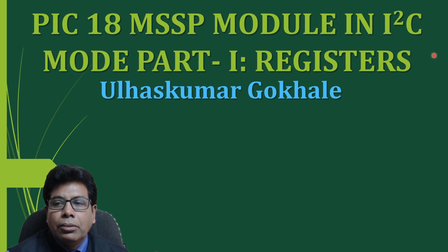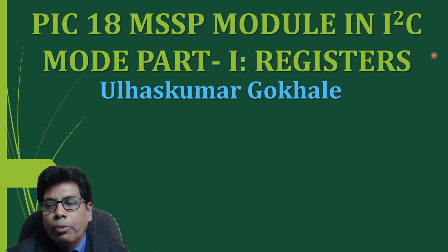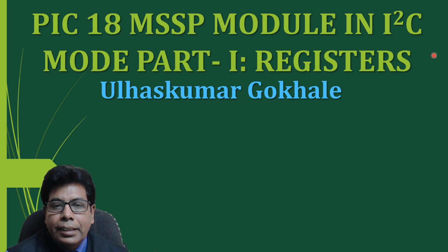The MSSP module in I2C mode fully implements all master and slave functions and provides interrupt on start and stop bits in hardware to determine free bus in case of multi-master function. The MSSP module implements the standard mode specification as well as 7-bit and 10-bit addressing.